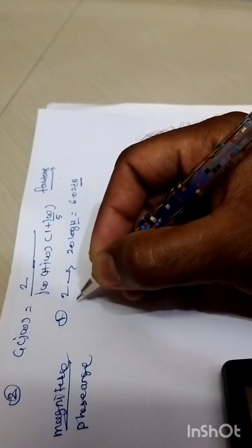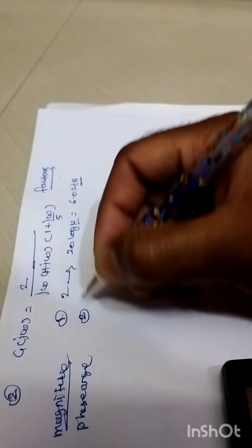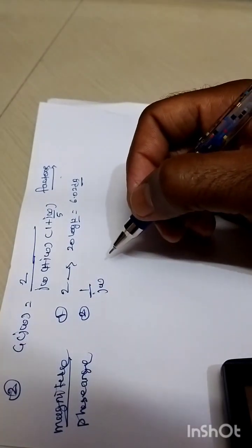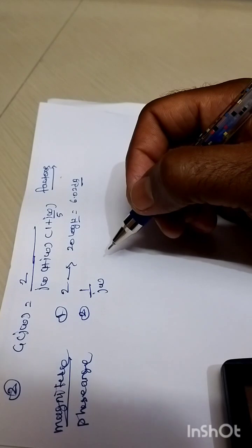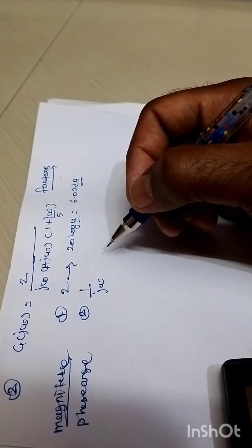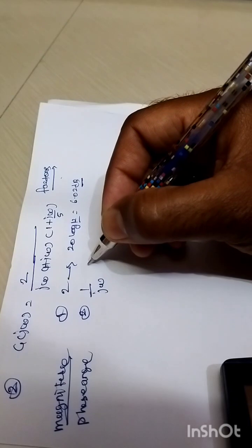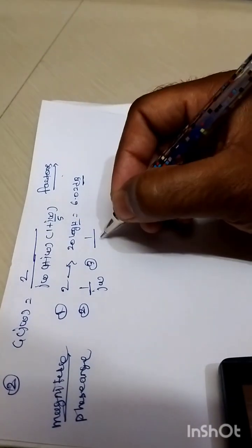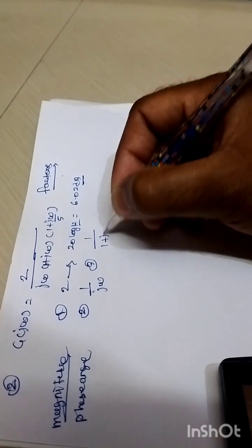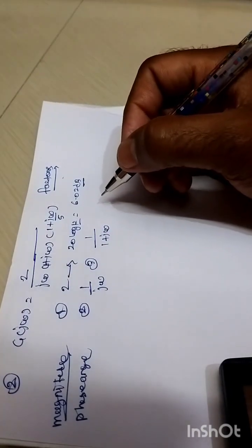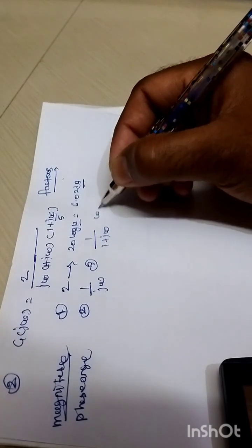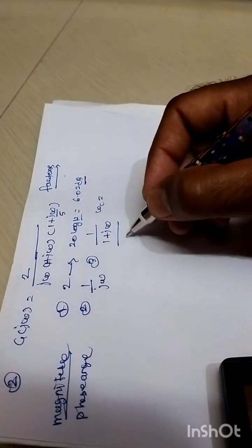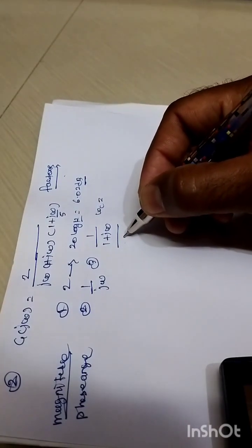Now the second factor is nothing but this pole which is present at the origin. Whenever we are having a pole or zero present at the origin, we are not having any corner frequency belonging to this factor, right? So immediately we need to consider the third factor whose value is 1 divided by 1 plus j omega, right? Now here we need to determine the omega c, the corner frequency of this factor, when this factor is represented in terms of S domain.